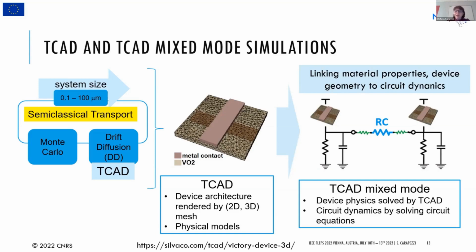Then TCAD mixed mode means to solve the equations of a circuit, not using what is commonly used, which means compact models. So essentially you have analytical formulas which describe the behavior of the device, but at each step you solve the circuit equation, and then you solve at this step also the device, you perform device simulation.